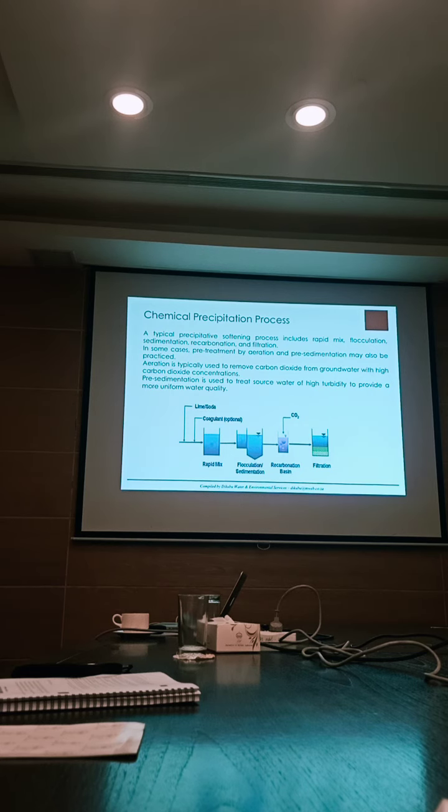We can pre-treat here as well. Remember I was talking about pre-treatment, aeration, ozonation, anything like that. Why do we want to pre-treat? Pre-treating is going to mean savings in chemical addition. Go and do the exercise. I can't tell you what is going to be cheaper for you. I can say to you that it's worth doing the exercise.